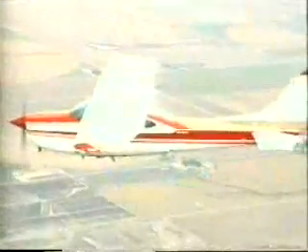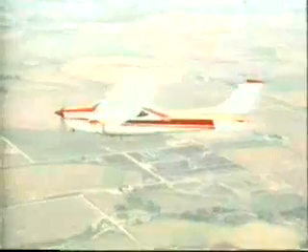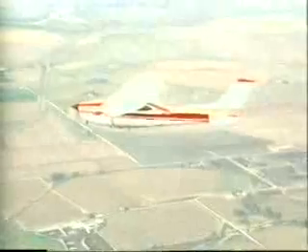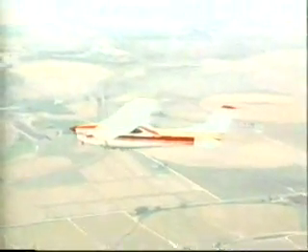The final variable in the lift formula is the wing area. Lift varies directly with the wing square footage, provided the planform does not change. This means that a wing with a planform area of 200 square feet produces twice the lift at the same angle of attack as one with only 100 square feet. That's why you'll find that airplanes with short wings typically have high camber to increase the coefficients of lift at lower angles of attack.